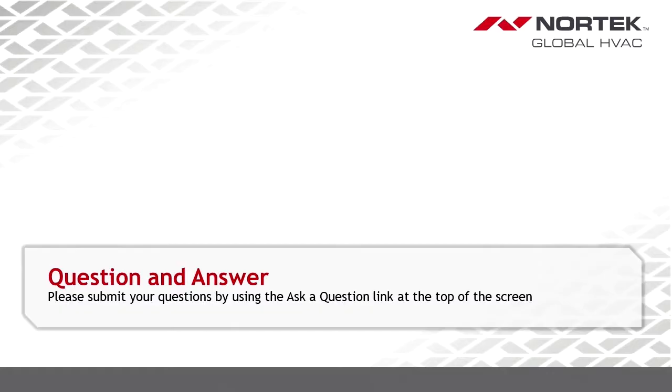We do have an adaptation out there that you can take outdoor relative humidity and plug those numbers in, and it'll give you a guesstimate on what wet bulb temperature might be within the house itself. But I would recommend that you pick up one of those digital sling psychrometers that will measure that for you. The one that I have measures wet bulb, relative humidity, dry bulb, all that neat stuff, and that'll make it a lot more accurate when you're trying to get the correct charge in there.